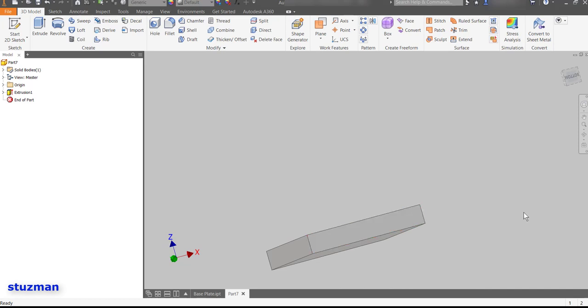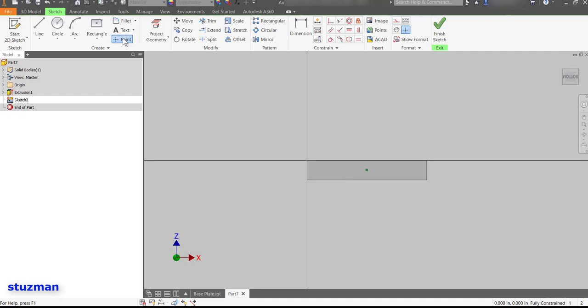Okay, now I'm going to go ahead and put the holes down in here. These will be threaded holes that go in on the bottom. So I'm going to create a sketch. I'm going to get my points again, put them there, and this time I want it to be horizontal with this point where all the axes and the planes intersect, because remember, that never moves. So that to this one, and now we're done.